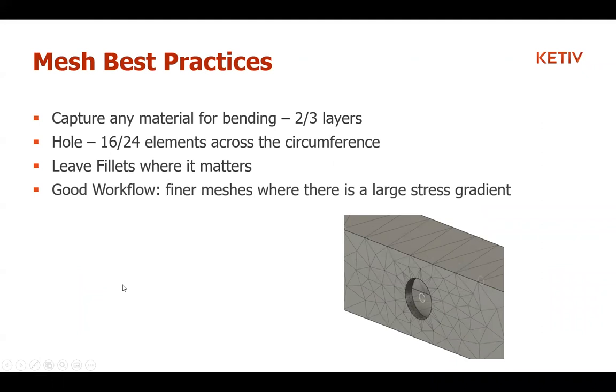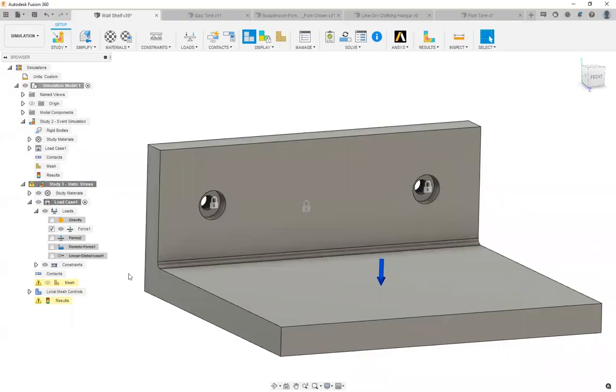A good workflow is to, where there's a larger stress gradient, you want finer meshes. So this one might be a little obvious as well. But where you have the most stresses, so let's go ahead and actually solve that so we can see the stress.